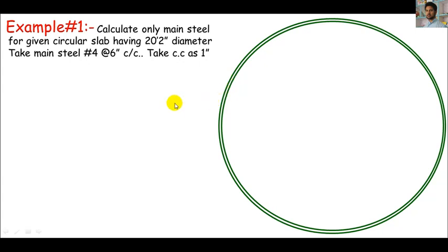So everything is given, everybody okay. I'll come straight into the solution. My approach will be calculation per main bar, and this is quite simple. But for the main bar calculation, I need the clear diameter. It means I subtract 2 times the concrete cover from the external circle.